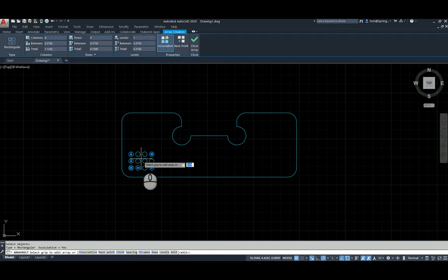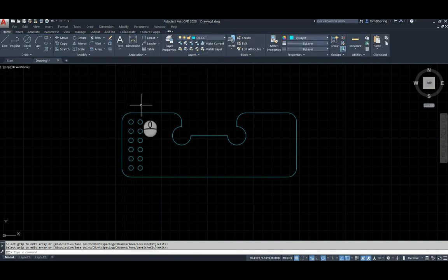All right, now here it gives me an array, and I have to tell it what I really want. So how many columns did we say? We said 2 columns, and then we said 6 rows. All right, boom, and then we do that. And the distance between them is 0.5 and 0.5. And when we do that, boom, it fills it perfectly. It looks great, and we can go ahead and click on close array, and there we have it.